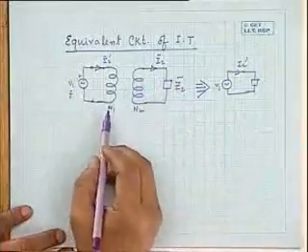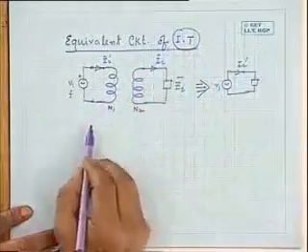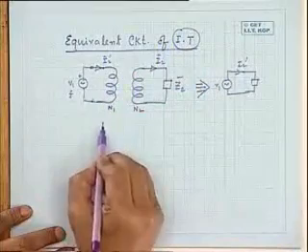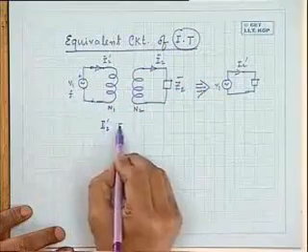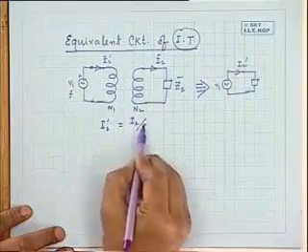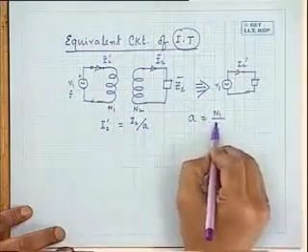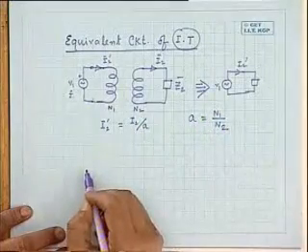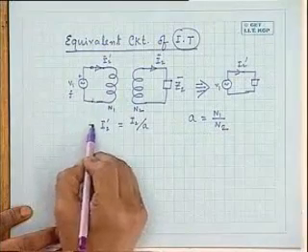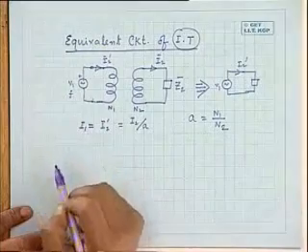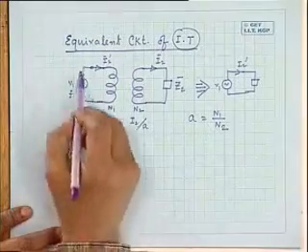Are you getting? That is, the question is, what impedance does the supply see connected across it? So that can be easily found out in this particular case. For example, in this ideal transformer, we know this thing. See, the magnitude of I2 dashed is how much? I2 by A, where A, you remember, is N1 by N2. And this is in fact equal to your I1 in case of an ideal transformer.